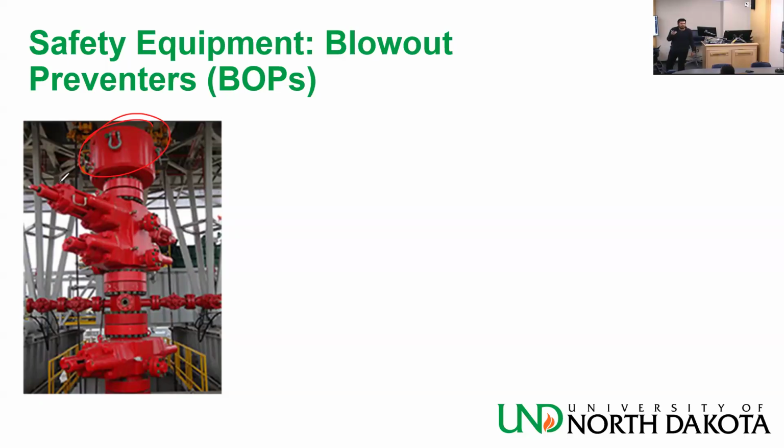I think Hydril was the name of the first company that made it or something. That's why this is the one that you use more often, and that's the one you can replace more cheaply. It's just a balloon that covers everything outside of the pipe. This stuff here, I can't tell which is which, but they're either blind ram, shear ram, or pipe ram.